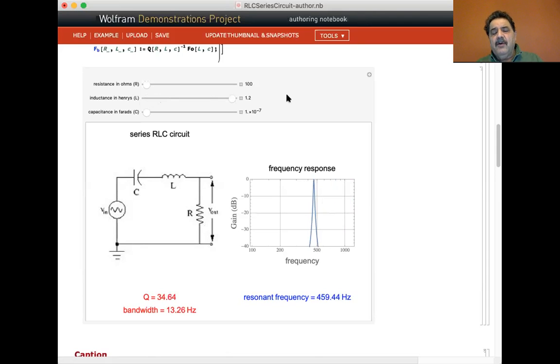It's much narrower. The bandwidth is determined where the peak frequency is your reference, that's 0, and it's at the 3 dB points on either side. Minus 3 dB is the half power point. So it's the half power point on either side that gives you the bandwidth.